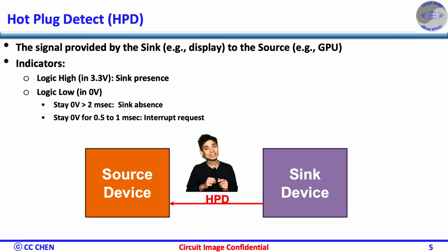The second extra link is the hot plug detect (HPD), which is a critical feature of most links and a must-have in most devices. For example, if you had to turn off any device, such as a cell phone, every time you connect or pull out a cable connection, that would be annoying. That's the reason most devices must support hot plugging, such that you can remove or insert any cable into your phone without turning the device off and on.